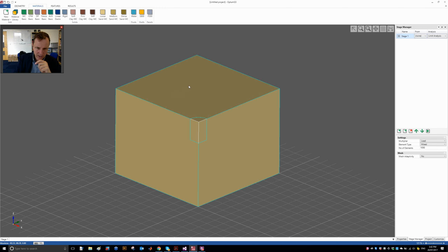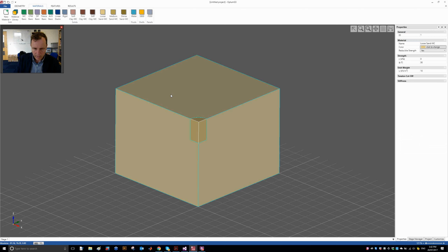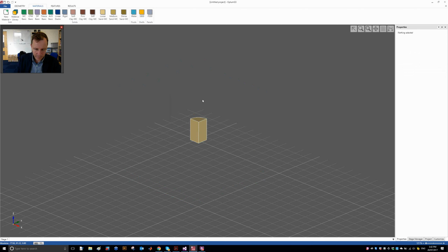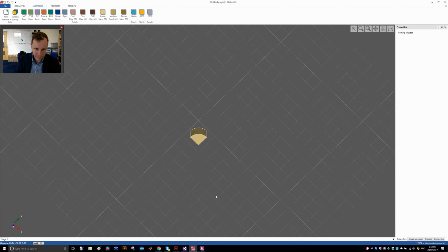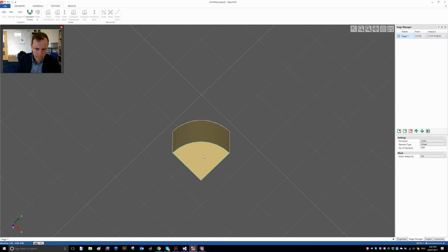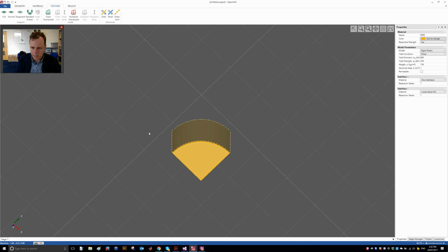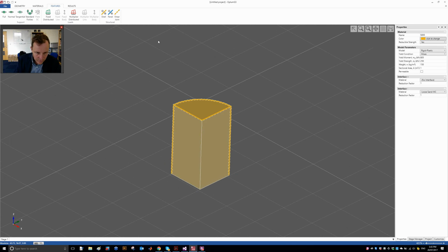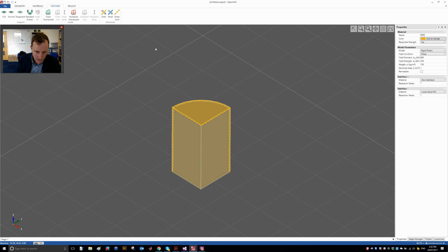And then to apply the shell elements, I first need access to this part of the domain where they should be applied. So I hide that part, and I now have access to the back here of this quarter cylinder, where I can then apply shell elements, both here and here. I don't know what happened there. So shells, and hopefully you can see that interfaces are included automatically as well.